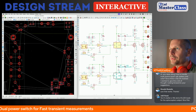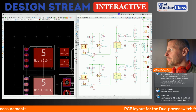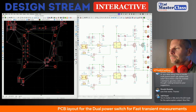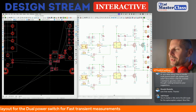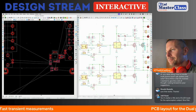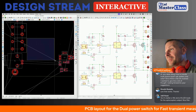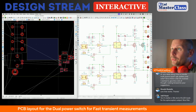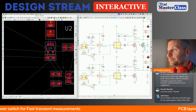The same for the channel 1 MOSFETs. There are 2 of them. So this is why I am steering the pathway for the signals downwards, and then I will go back upwards, because I need this area to be undivided, unsplit, for usage as a heatsink.